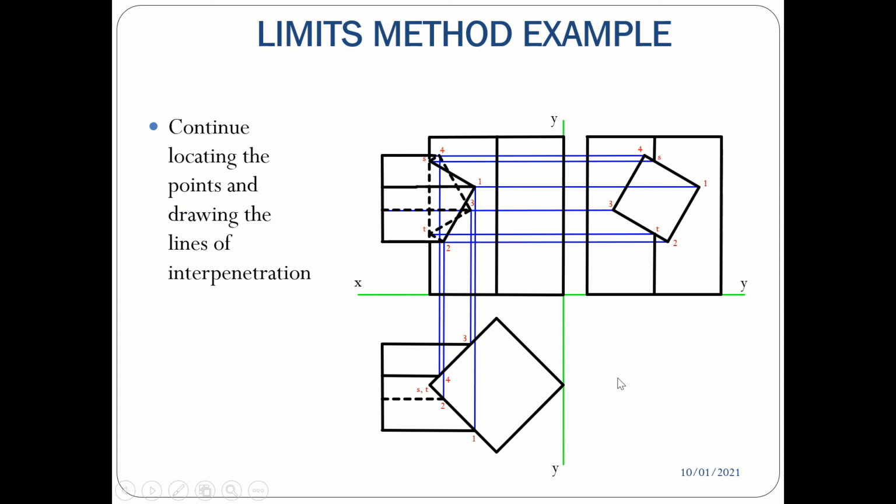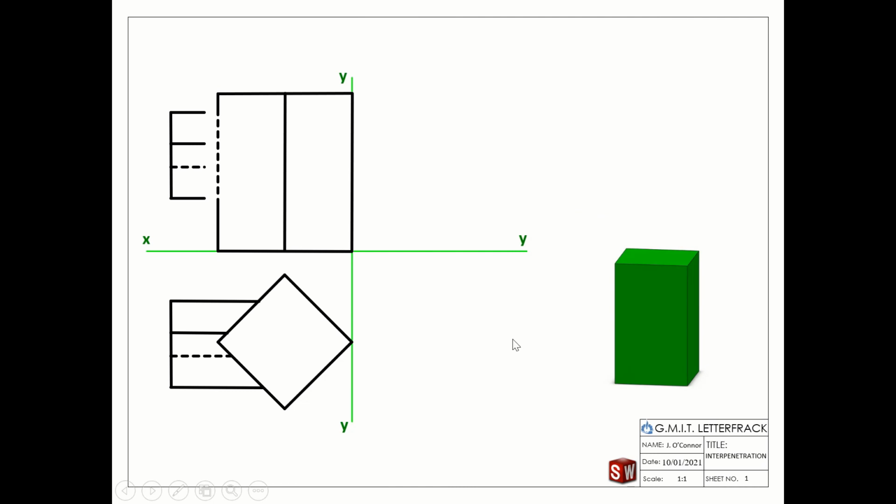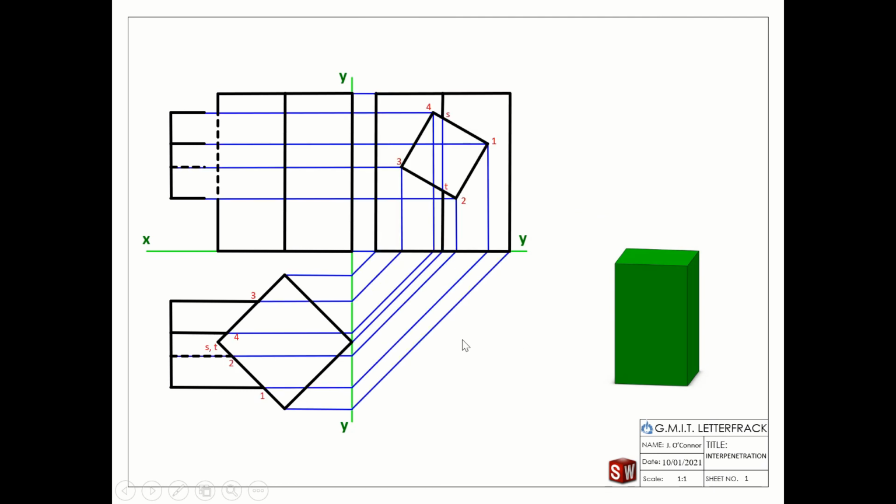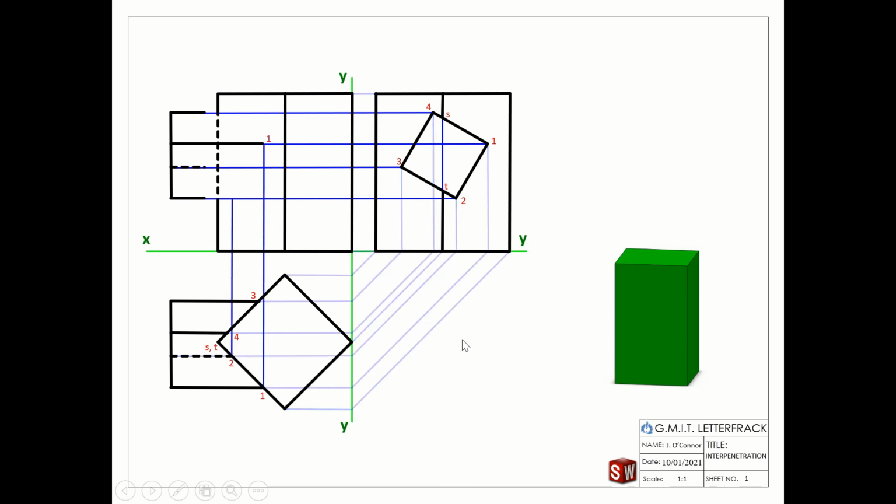So that's a look at the first example. And if you want to see that there in color again, I can just roll through that quickly. So set up your end view, label everything, and match your corresponding points, 1 to 1, 2 to 2, etc. Now, whether you want to get all your points first and then finish it out, or do it as it's going along there like an animated question, that's totally up to yourself. But please, please label your points or you're going to get lost, because they're going to get much more complex later on. So that's the intro there, folks.